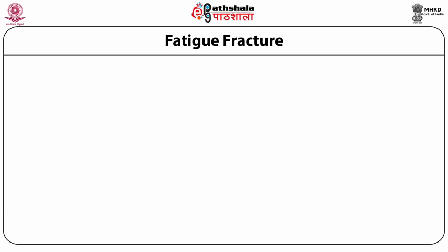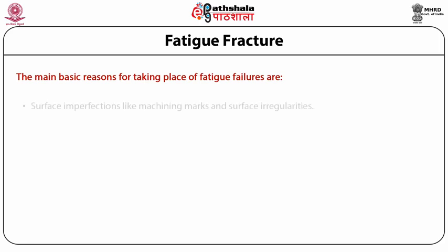Now let us see the main basic reasons for taking place of fatigue failures. The first basic reason for the fatigue failure is the surface imperfections like machining marks and surface irregularities.